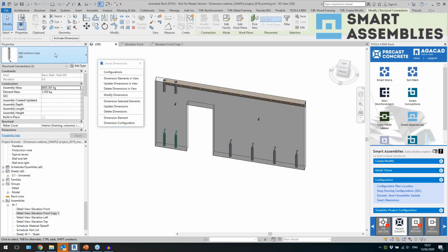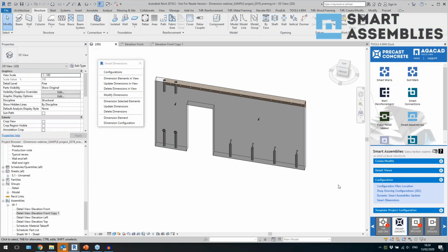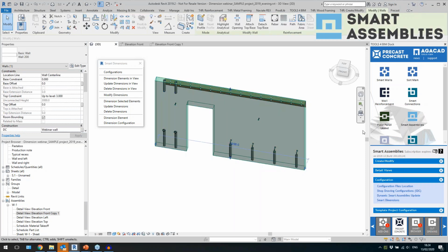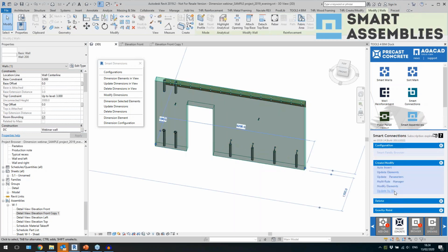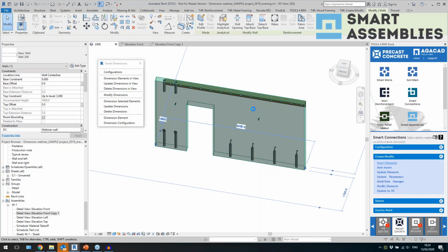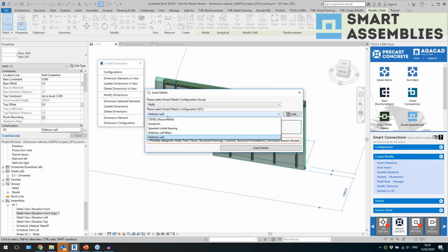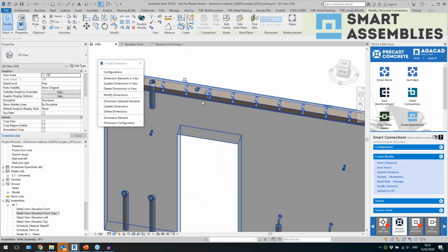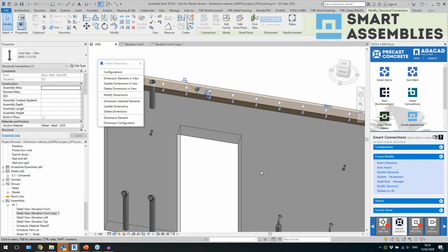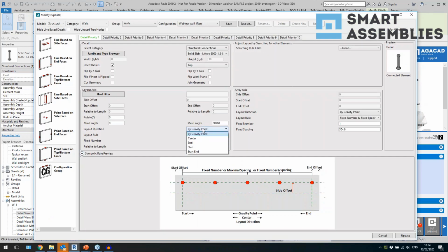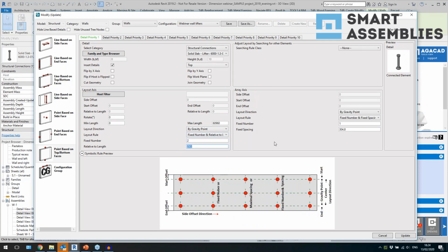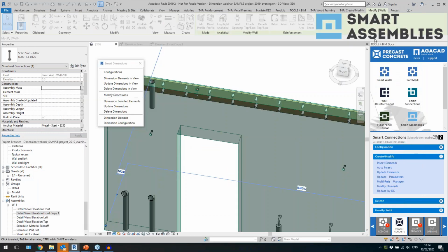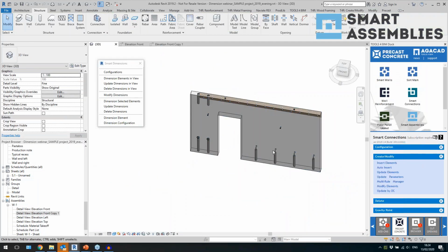For example, I'm just gonna change these, let's say, to other family, and then I can also use smart connections one more time to insert something else. For example, insert elements, and I will say that I want to place another configuration, just some lifters. So these guys are placed by gravity point. So I can define that they should be placed by gravity point, 2 of elements, and some more than half of the wall length should be the distance between them. So one here and one here.